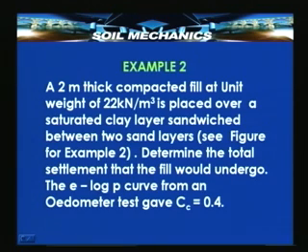It is a different matter that this fill material is a flexible material, this layer is a flexible layer, and even if there is a lot of settlement in the succession of natural soil layers which are below, the fill layer can still adjust.